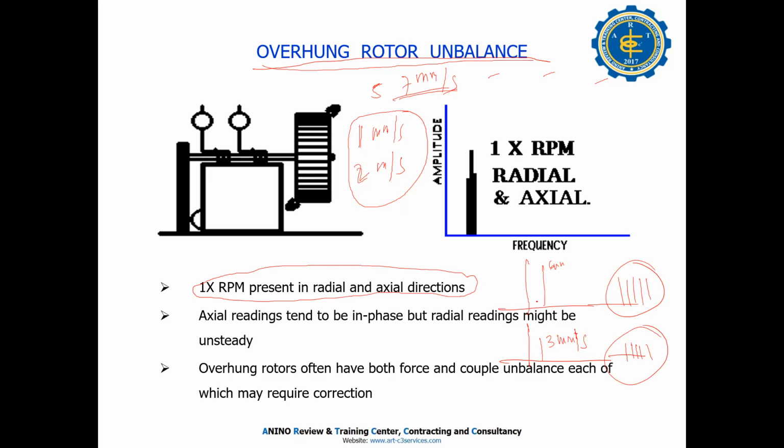See? You know the difference: high vibration, 6 mm, no harmonics here, it's good. 3 mm per second, low, but there are harmonics here, meaning you have starting looseness. Okay, a problem with your bearing. See, that's the experience.